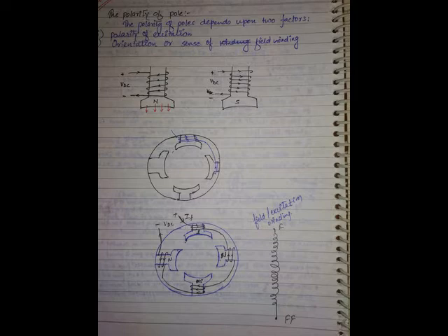What you are doing means, without reducing the cross-sectional area, you are making the solid core act as, you can think like this, each lamination acting as an individual core to form a single core. Can we say that? Each lamination is now one core.